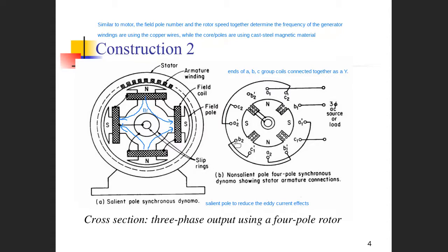So in such a way, when we use the pole materials, we have to make the pole materials have a bigger internal resistance. That means the current cannot go from one piece of the poles to another piece, so that the eddy current inside is smaller and the core losses are smaller. That's the basic idea.